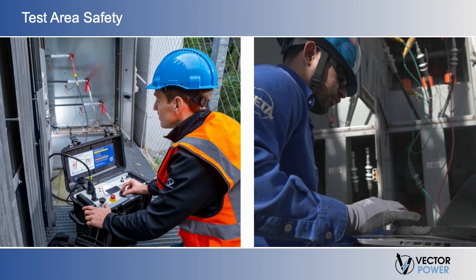When performing electrical testing, we temporarily energize the circuit with a test potential or voltage. The device under test is now energized and presents an electric shock hazard. Energy control safe work practices must be followed to mitigate this hazard.